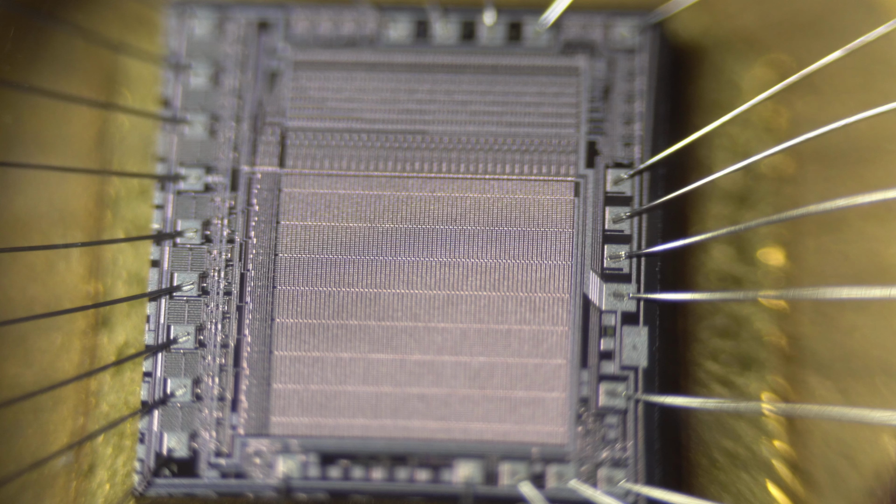Today we have NAND flash, NOR flash, and of course magnetic storage. Each type of non-volatile storage has a different limited lifetime, and once they start to wear out, you can expect to see bit flips. Even with NAND flash specifically, there are many different subtypes that can have dramatically different lifetimes. Some of these storage media can include their own internal mechanisms to try and correct bit flips, but multi-bit flips